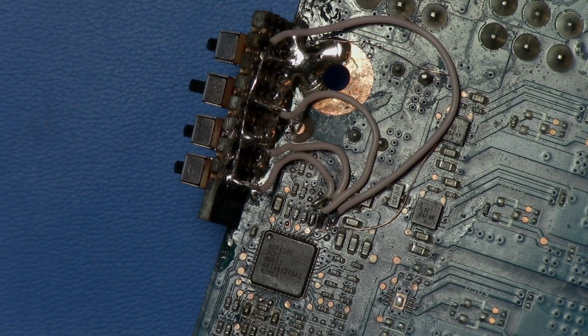So I just would wire in the 4 switches like I did. If you wanted to not solder to VID 5, just solder to VID 6 instead. So do 6, 4, 3, and 2. And with that and a feedback mod, you can get more than enough control. Actually, even if you just do 6 and 4, you can already get your either 1.2 or 1.4 volt VIDs, and then just use a feedback mod from there. So yeah, I would actually just say that is what everyone should do if you want your full voltage range to be able to control it. And anything beyond that is just extra.